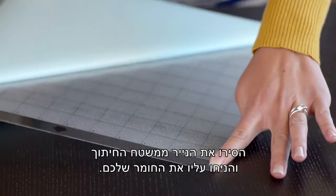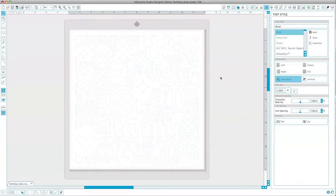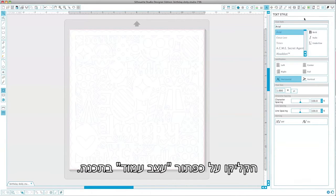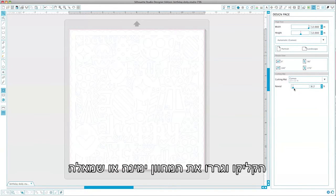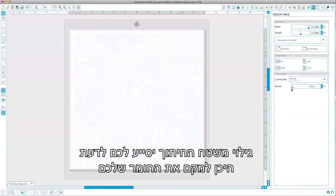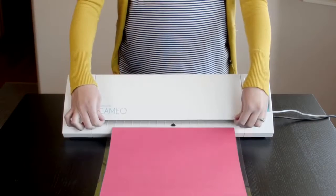Remove the liner from the cutting mat and place your material onto it. In this example, we will use cardstock. Silhouette Studio will show you where your materials should be placed on the mat. In the software, click on the Design Page button. In the Design Page panel, click and drag the Reveal slider right or left to show or hide the software cutting mat. Revealing the cutting mat helps you know where to position your material on the actual cutting mat based on your design. Lift the lid.